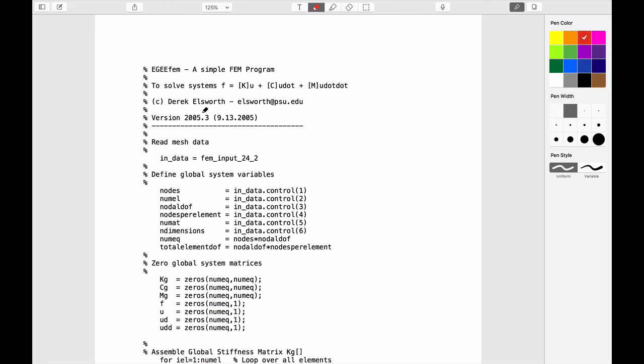So the next step up, if you like, again looking at some more coding, is to take this and define it in how Matlab would solve it. And any finite element code basically does the same steps. What it would do is define the problem that you're solving. The particular problem we're solving is the one we've talked about so far in terms of conductance matrix. It would want to know what the information is that define this matrix.